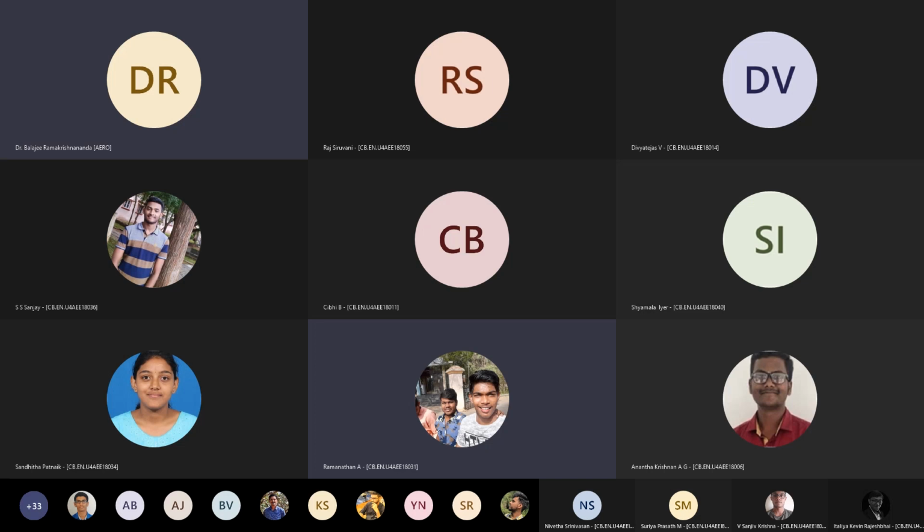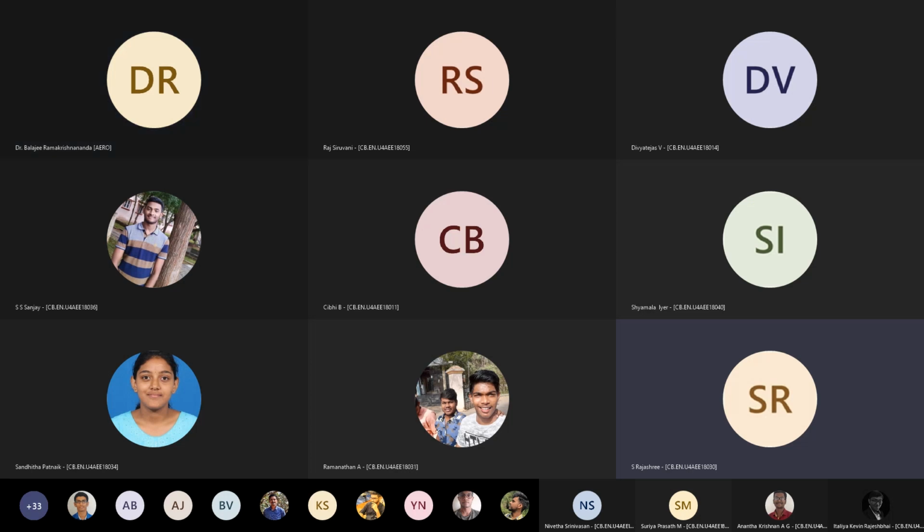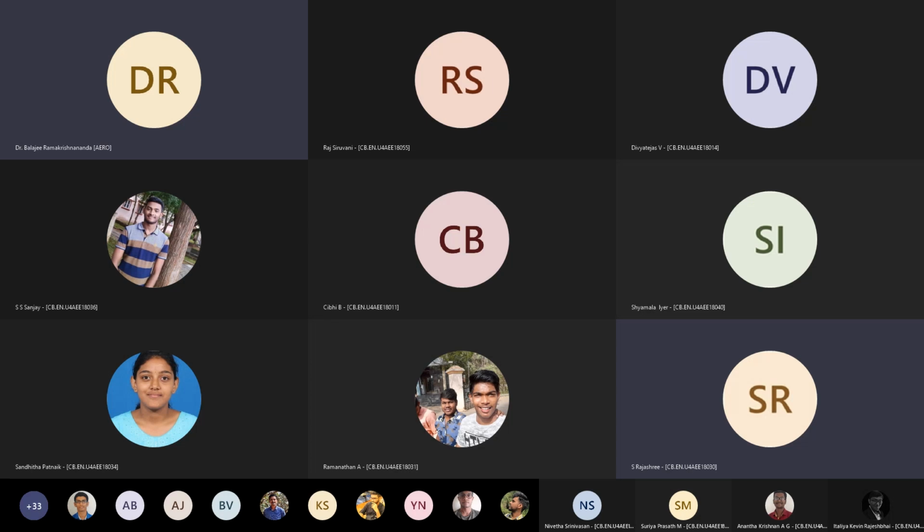Now Rajeshri has a question. Sir, you were showing a plot of thrust to weight ratio versus wing loading for cruise, and you said we have to vary the cruise velocity and see how that varies. We just have to find the feasible region. Your cruise velocity should be at least more than what is given to you. If you cannot achieve that velocity, then you are falling short of the requirement. So to determine that, you vary the velocity and see which side is feasible.